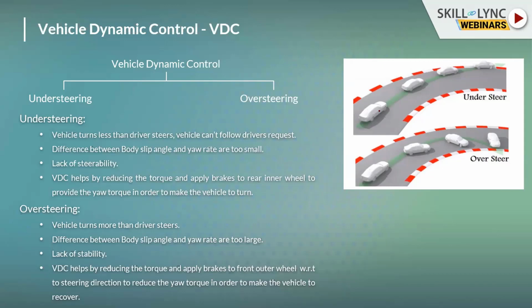What the VDC will do is, we are moving at a certain inertial force, and we need to change the inertial force, then only can we make the turn. If we are moving at a slow speed, we can directly turn by means of steering input. So the translational velocity will be shifted and we can turn. But at high speed, the inertia will be more. Because of the inertia, we need to change the inertial force, which is pointing in a certain direction.